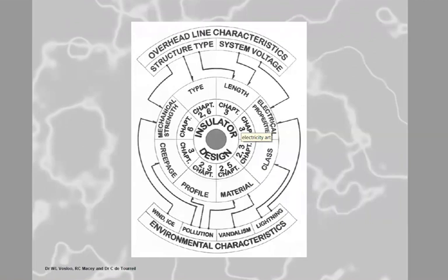Also, you'll do arc resistance tests, where you do a power arc test across the insulator surface to take a look at where the insulator can withstand different electrical aspects of it.